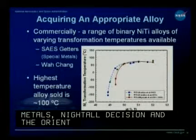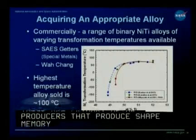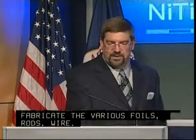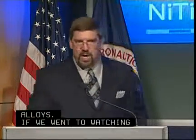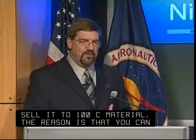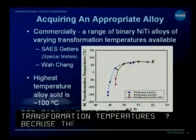Those are primary metals producers that produce the original ingots of shape memory alloy. Those can be sold to dozens of other secondary producers that then fabricate the various foils, rods, wire, tubes, and other shapes for the shape memory alloys. But if we went to, say, Huacheng and we asked them for their highest temperature material, they would sell us 100 C material. Now, the reason is that you can actually get shape memory alloys in a number of different compositions for use over different transformation temperatures, because the transformation temperature itself is a strong function of stoichiometry.